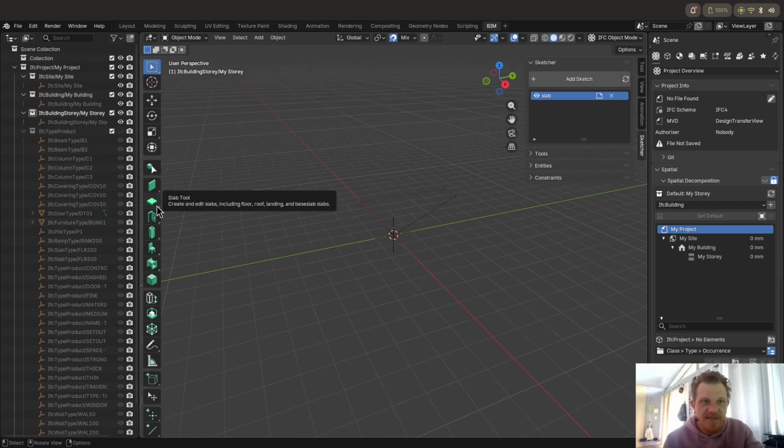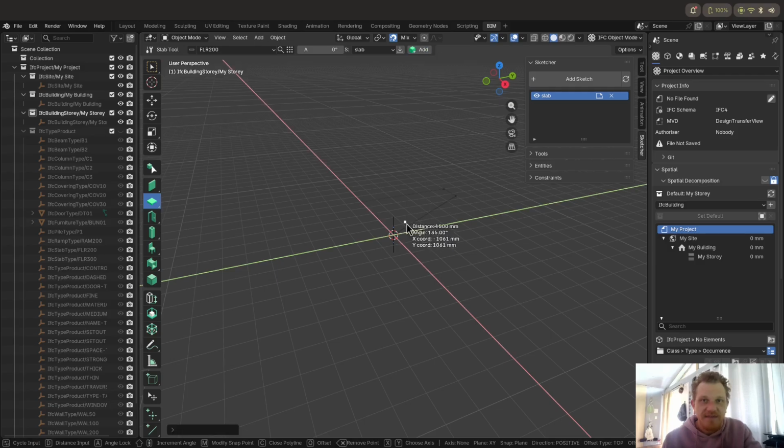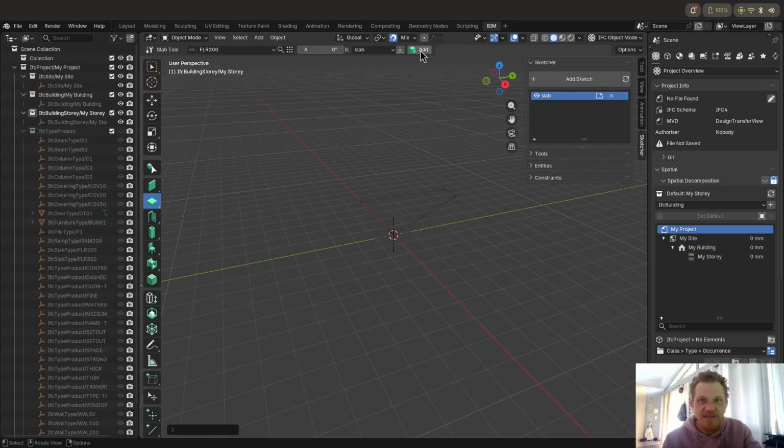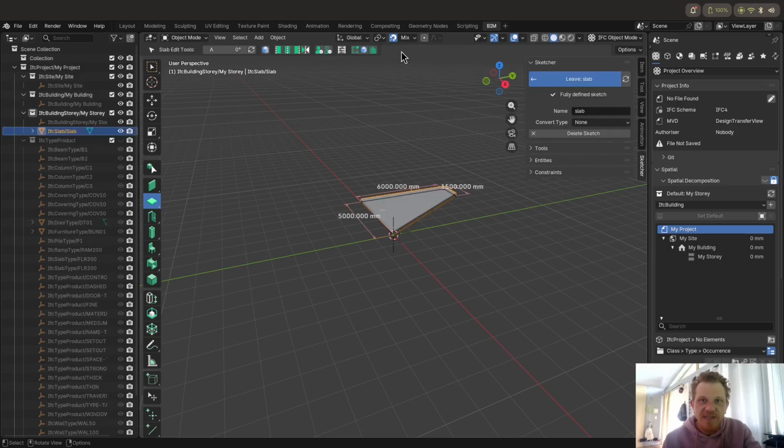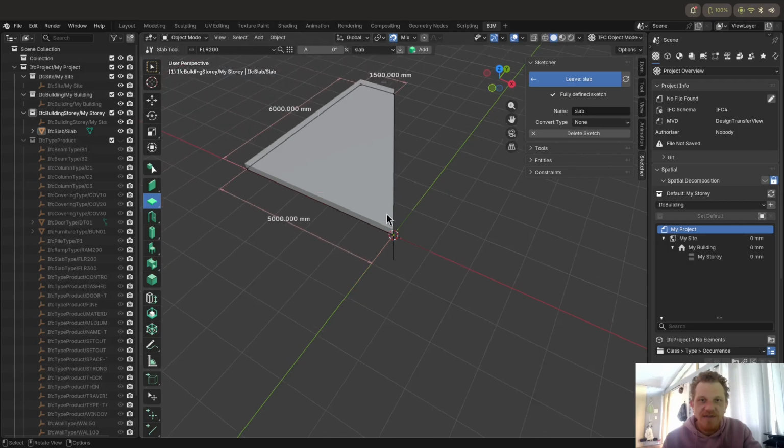here let's add a slab tool. We can see that we have our slab that we can select. That's from the template that we opened. And now here we can select a sketch. We can add a slab like before, but that's not our intention here. We want to add this slab in this type of slab in the slab catch. So we just need to click here, and then it does the conversion, and our slab is created.